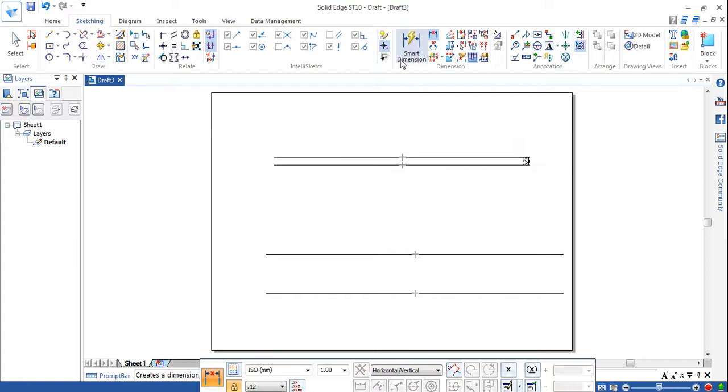Okay. Then similarly I'm gonna give these lines, and the distance between these 2 lines is pitch divided by 4. Please note, this is pitch divided by 4. This is 12.5 mm.